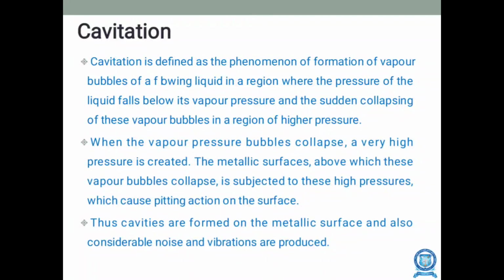What happens actually is that vapor bubbles will be formed when the pressure is below the vapor pressure. What will happen when the bubbles collapse against the tubes or anything else? They will collapse with high pressure, so it will lead to brittle failure. The pipes will be broken off, or will have small tears or anything else. So we have to avoid cavitation.